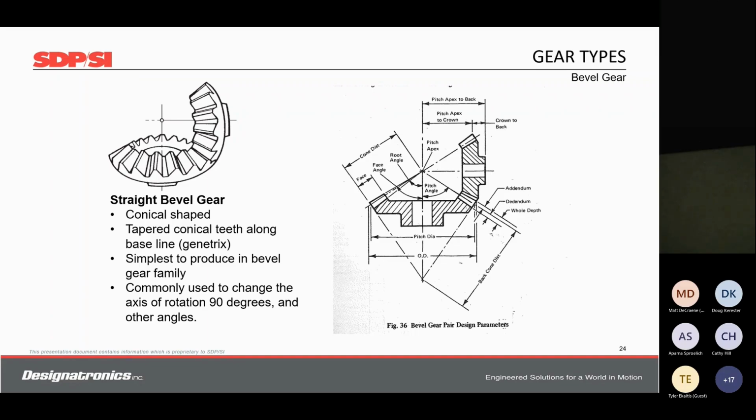We suggest an accurate banking step or wall to contact the back of the bevel gear to find that pitch apex to back. An alternative, which a lot of our customers do, is to clamp or temporarily attach the bevel gear, find the proper backlash or function, and then drill and pin or use another type of permanent attachment. A lot of customers use our spray lock in those bevel gears, and once it's tight, it doesn't go anywhere. So not only can you adjust and find that location, but once you tighten it, it's not going anywhere and can be used for servicing. We'll talk about the spray lock a little later.